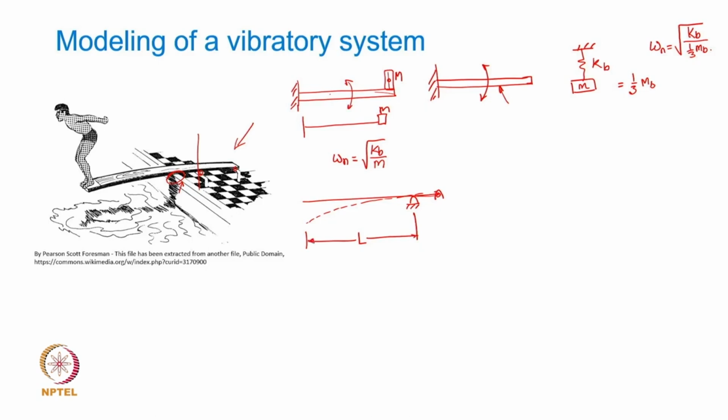When it swings up and goes beyond this equilibrium position, the deflection will be fulcrumed around this, because if it goes up and loses contact with this support, which appears to be the case here, then in the upper half of its rotation or vibration it will have a different effective length than it has here.